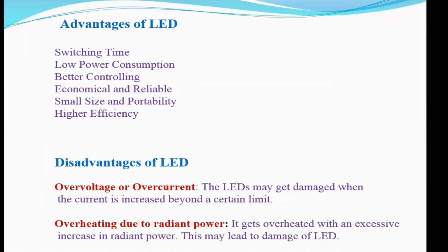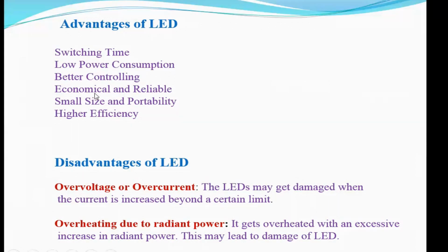Advantages of LEDs, they have fast switching time. The switching times, that is the on and off of these LEDs, can be done within less than few microseconds, and these LEDs consume low power and have better control. As I told before, we can control the brightness of the LED, that is the intensity of the light, by controlling the current passing through the diode, and it is economical and reliable. These LEDs are available in smaller size, so they are portable and they have higher efficiency.